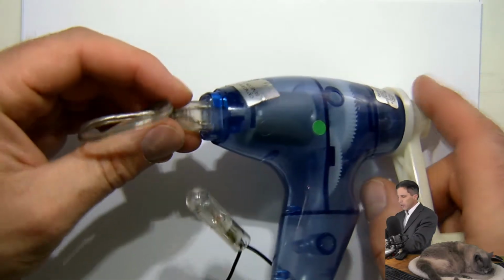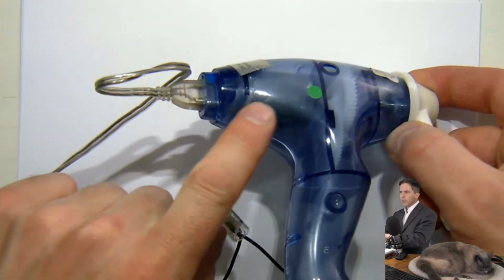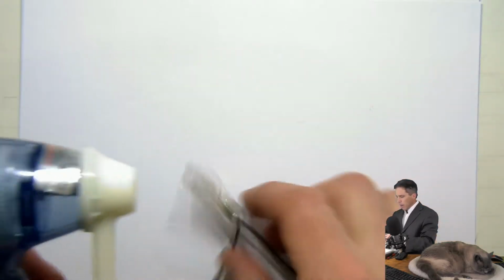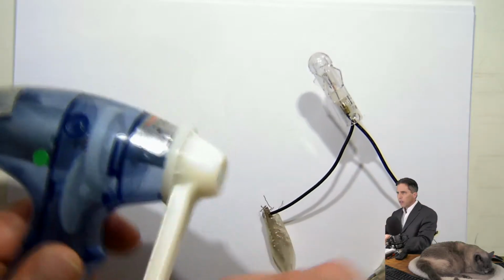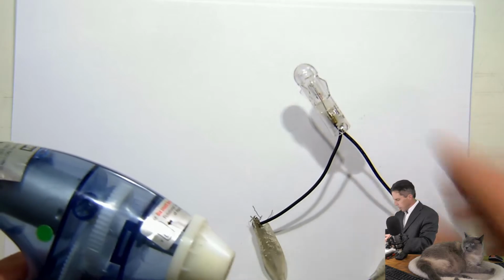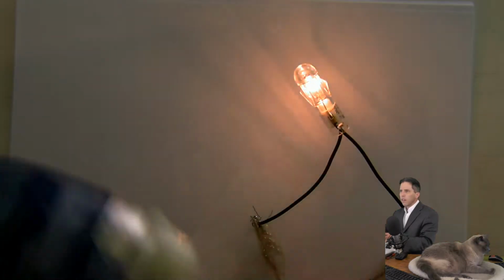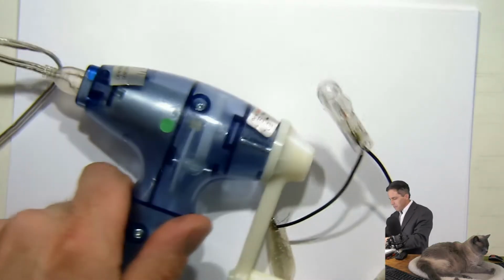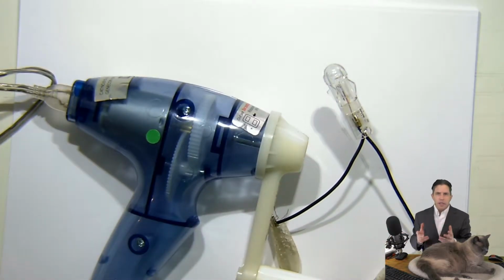A simple demonstration is, so you may have seen something like this, that this is a hand crank generator, and inside there's a little, you see that little metal cylinder, that's got a magnet in there, and when I spin the handle, okay, the light lights up, okay. So you need three things to generate electricity: magnetic field, conductor, and motion.